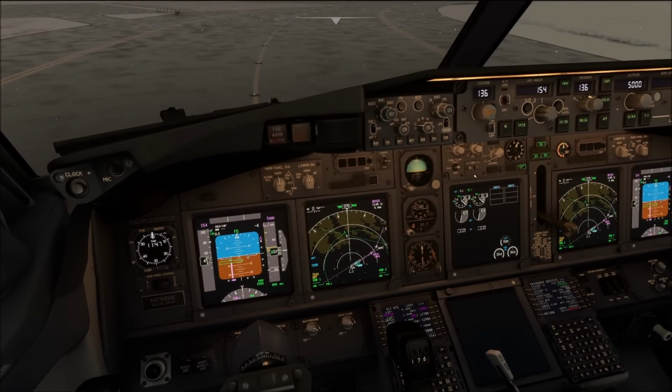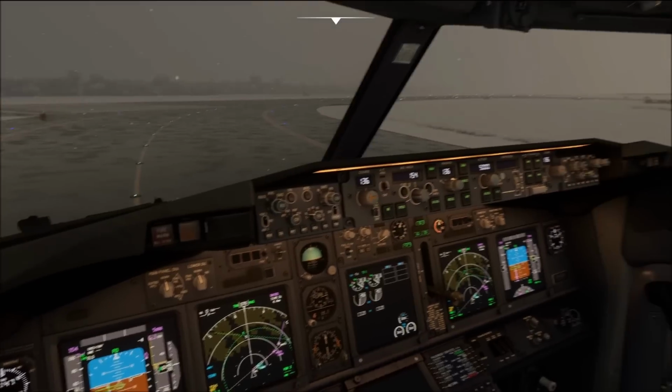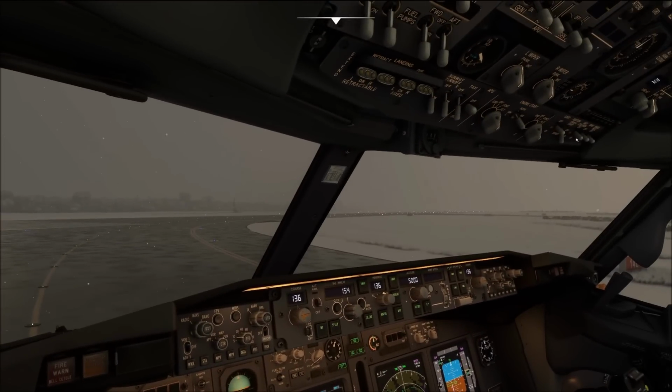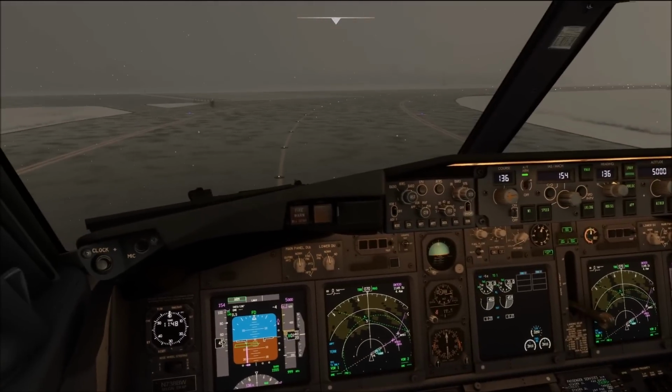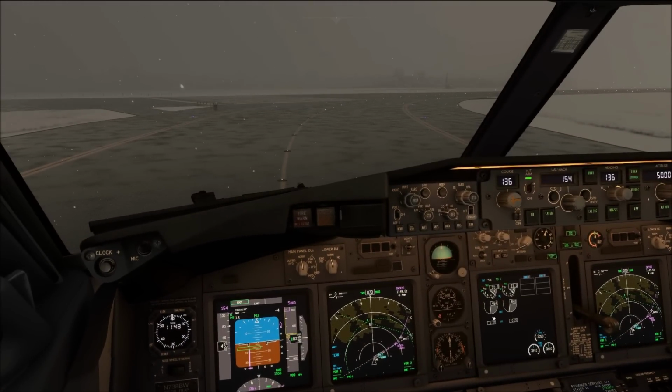Okay, from here on we carry out the normal before takeoff checklist, and once lineup clearance is received, we are going to line our airplane up on the runway, and we have one final thing to consider during that procedure. So let's go ahead, assume we have just gotten our lineup clearance and our takeoff clearance. The first thing you need to do is to advise ATC that you will take some extra time on the runway, as you do need to carry out some additional procedures there. And these additional procedures basically are the ice shedding procedure, which I'm going to talk about in a few moments.